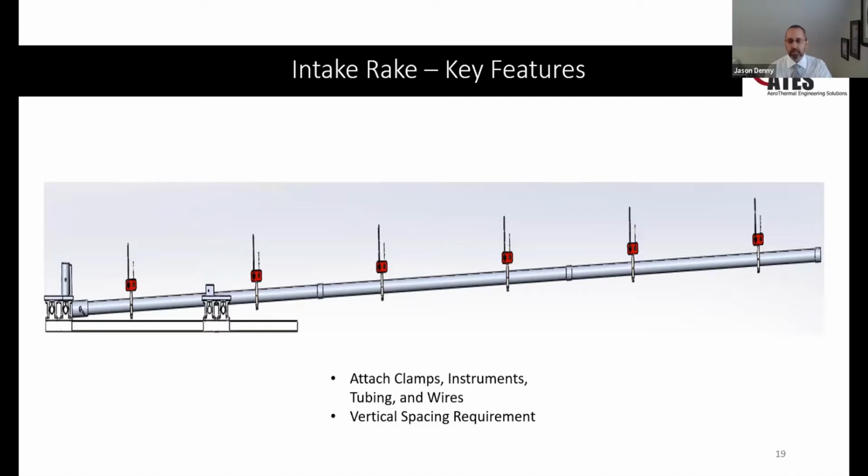And they can attach these anywhere along the mast except for the coupling places and the place where the brace support will attach, which was not an issue for us. So that covers our requirement for our vertical spacing, which was 2 feet and adjustable up to 4 feet.